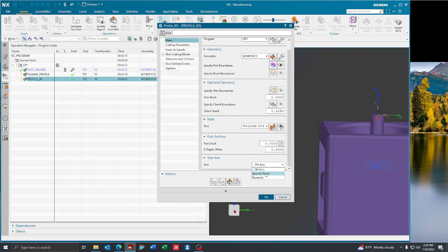By manipulating tool axis vectors, you'll be able to sneak tools into places that you may not have thought you could get into before. The beauty of 4th and 5th axis machines is you can shrink your tool setup down by manipulating your tool axis vectors to get into tighter locations and not have to have such long stickouts or gauge lengths.